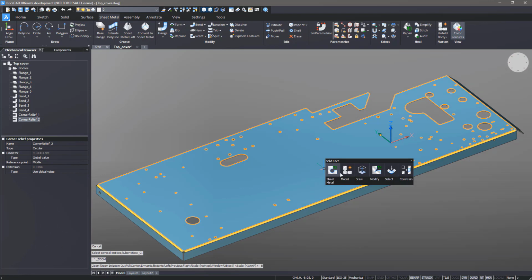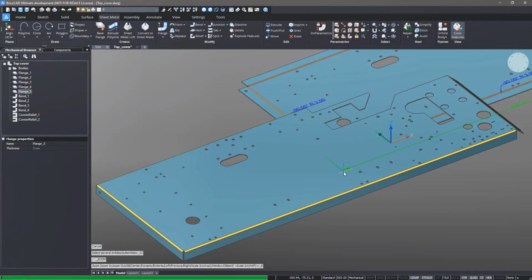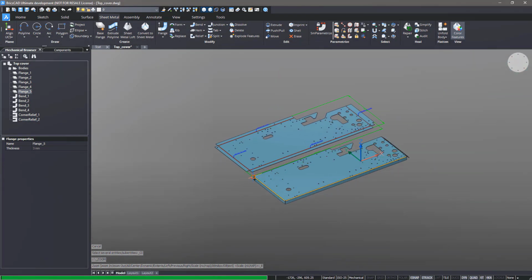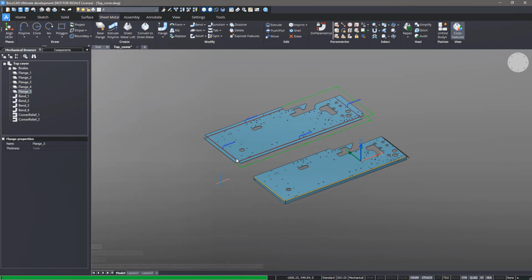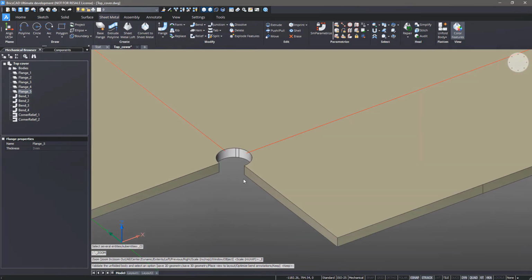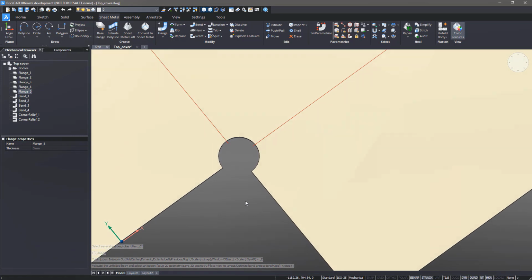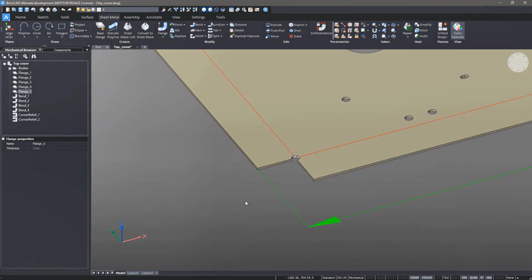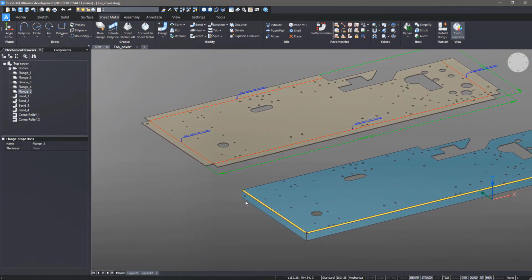In order to prove that we can unfold, and you see it's the interaction of all the commands and the bend table, that is why right now we get a perfect circle here. And it can be important because making circular corner reliefs is usually cheaper.